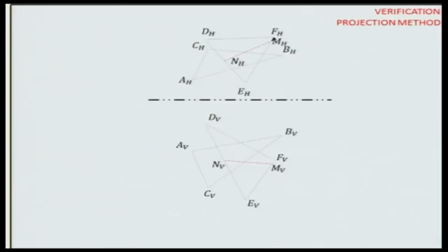Now, to figure out the visibility using projection method. So a few lectures ago I said that I did not get any logic behind the projection method, but it looks like there is some logic, and the logic is as follows. First things first, you realize that all these edges, they are going to be visible. All these edges, they will be visible. Okay?